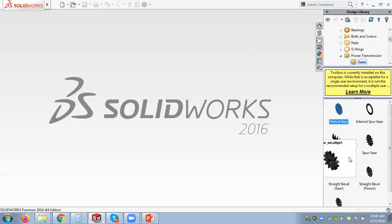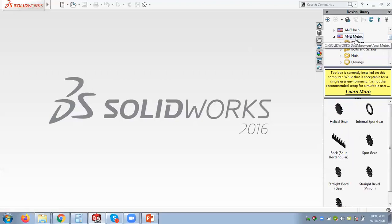Excuse me, sir, when we click the toolbox, we get a message that toolbox is currently running, and it asks for ANSI, ISO, GB standard, metric. What should we select? Normally, I selected ISO metric in mine. I select metric. It's about millimeters. ANSI is the American National Standards Institute. Normally we will use metric. If you haven't installed this, you need to do that. You can follow the process they ask, or else you can look at YouTube and install these libraries.